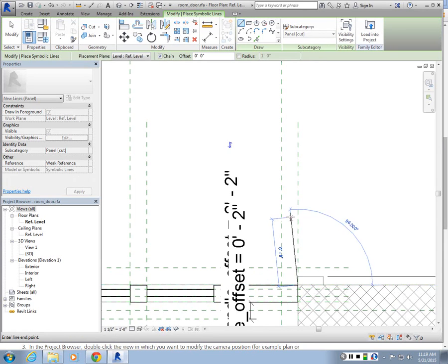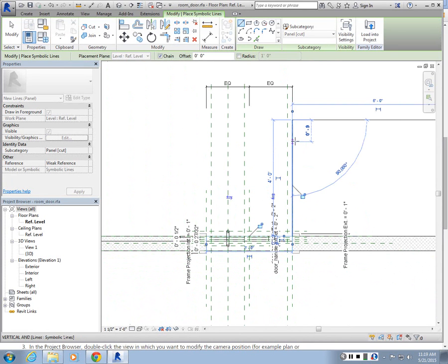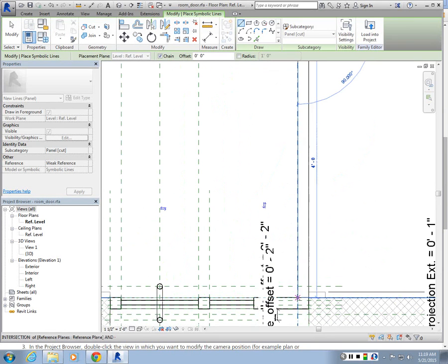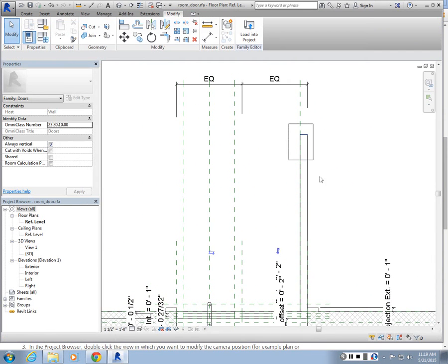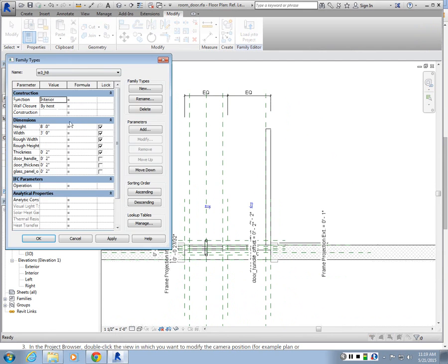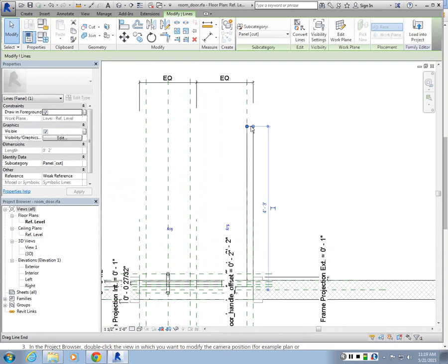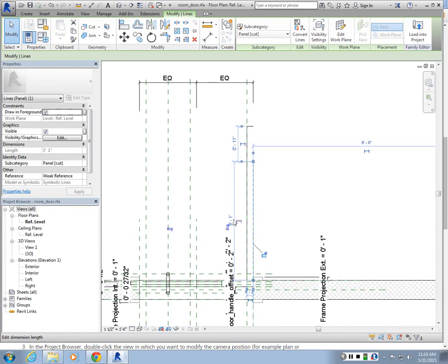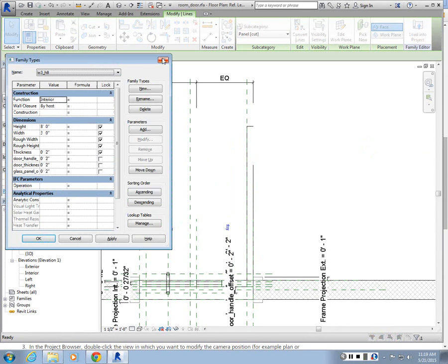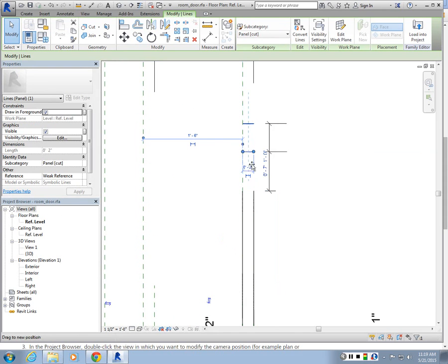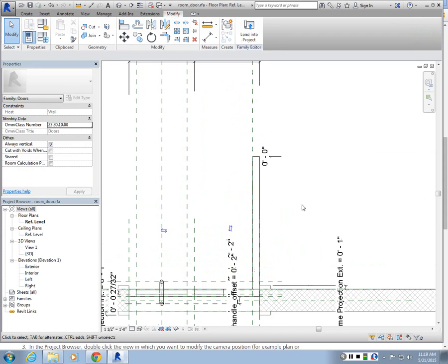I'm going to come in here, go up by 4 feet because it's a 4 feet door. Come down here with the door thickness, which is 2 inches, and then come down here and then close it. So I basically have drawn these two-dimensional lines. And then the next thing I want to do, actually let me first check, my total width was 3 feet, so let me change this to be at 3 feet. No, we are in the family. I'm changing this in the family so that it could take effect everywhere, yeah.